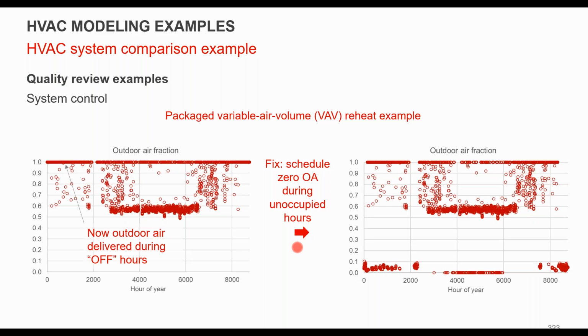A lot of times you might have high solar gains in adjacent zones as well that weren't separated when you were doing your thermal zoning. So you might have internal heat transfer from one zone to another that's causing unmet hours as well.